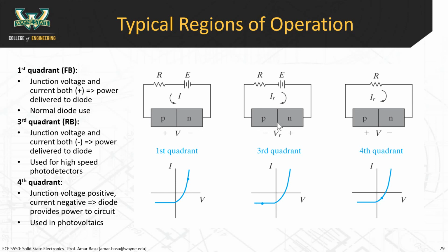If you have more electric field, you generate a carrier, and that electric field rapidly accelerates that carrier to the two sides of the junction. More drift. There's more rapid drift. The velocity is higher because the electric field is higher. And guess what that means? That actually means that your device is faster.